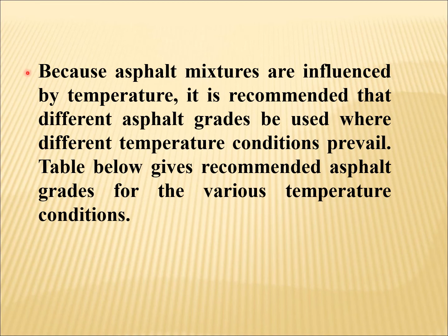Because asphalt mixtures are influenced by temperature, it is recommended that different asphalt grades be used where different temperature conditions prevail. So this point is very, very important, and I will repeat this. Because asphalt mixtures are influenced by temperature, with the increase of temperature, what would be the effect on the asphalt?